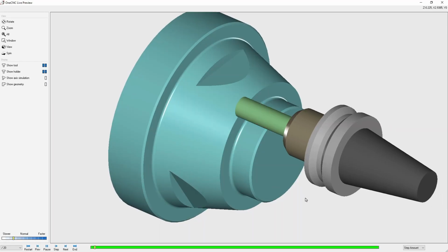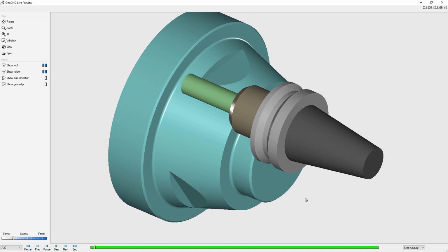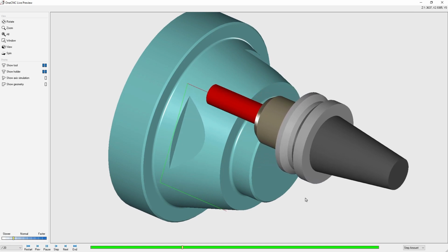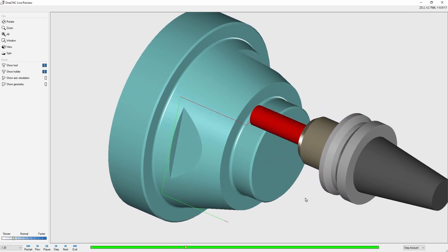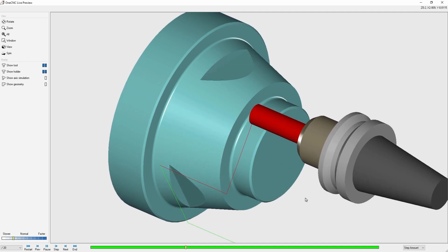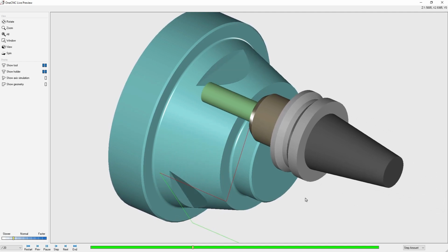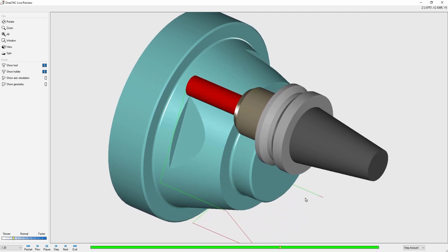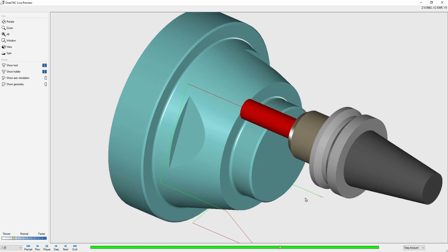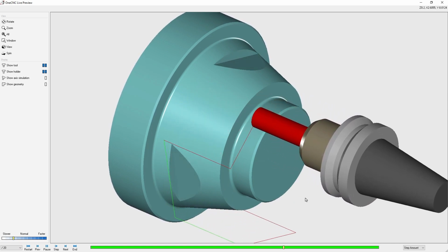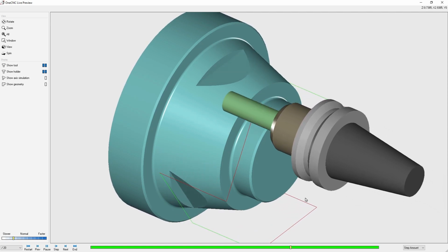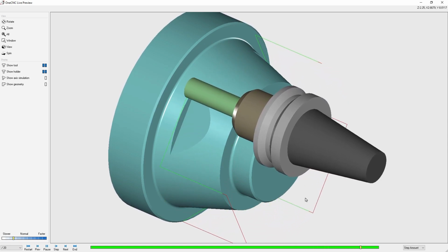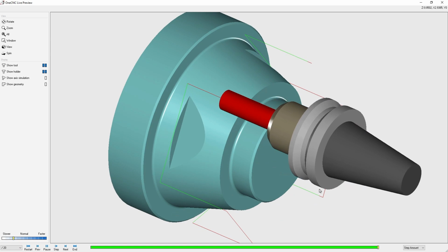Alright, so we can see the tool approaching the notch. It's starting 400 thousandths away, machining the notch, going past 400 thousandths, rapiding up to 200 thousandths above the part. Remember, that was our Z clearance level of 200 thousandths. Going to approach the notch, machine the notch, and then rapid back up again. Very good. Let's take a look at the final notch here. Tool rapids to position, starts 400 thousandths before, machines the notch, and then pulls back out again.